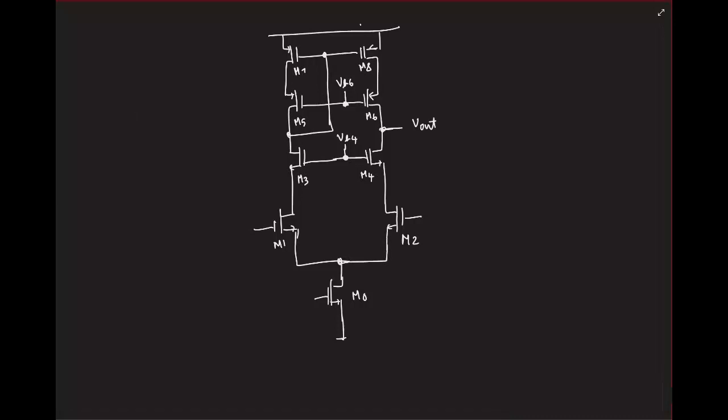Okay, so now here we know everything. Everything is now at a transistor level. The only thing pending is generation of the two other voltages, VB4 and VB6, right? And again they will have their own ranges for proper operation. Let us say I want to choose these two voltages so that my Vout will be at its maximum swing of VDD minus overdrive 8 minus overdrive 6, and at the minimum side it will have whatever it is. Okay, so let's see how we can generate quickly.